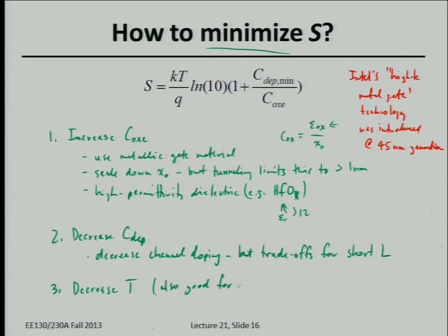for increasing the effective mobility. Okay, so if you decrease the temperature, you can have steeper subthreshold swing. So that means you can design your circuits to operate with lower VT, so you have higher current, faster speed, and the fact that the effective mobility improves also causes your circuits to operate at high speed. So there are computers, I don't know if you've heard of Cray computers. They operate electronic circuits at low temperature to get higher speed, higher performance.